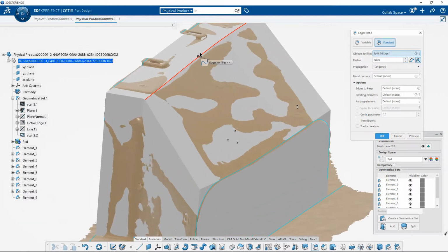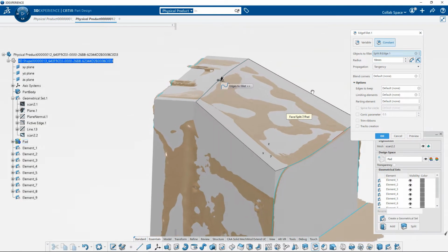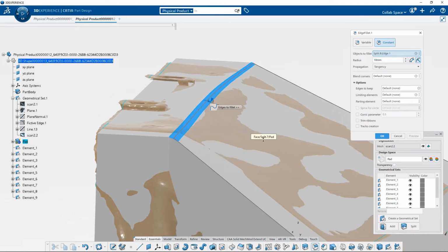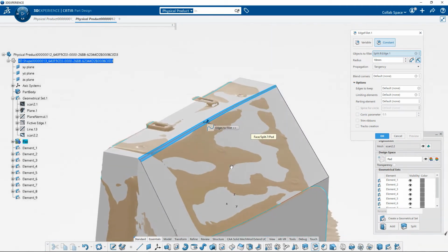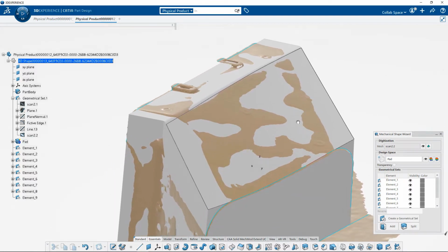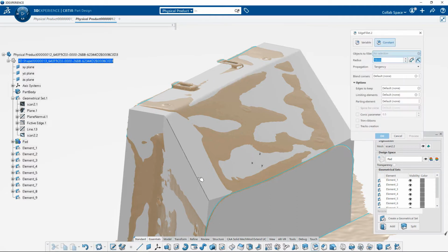But now, okay, first operation, classic mechanical design operation, create an edge fillet along that edge of the object. Either you know the value of the fillet, or you define it visually by trying to fit to the mesh. Okay, that's classic, really classic mechanical design. Second operation, so create this bigger fillet here.